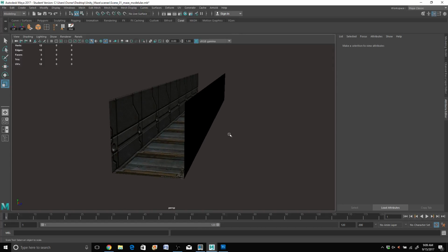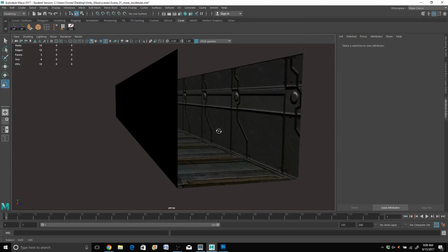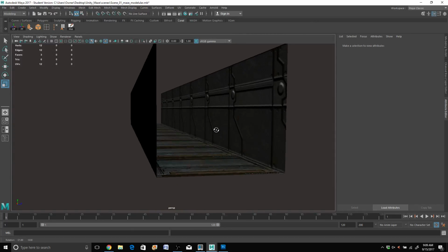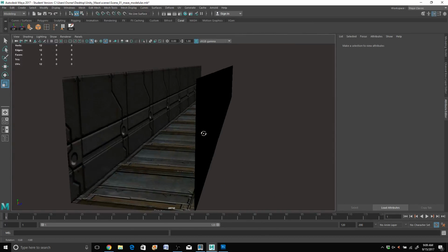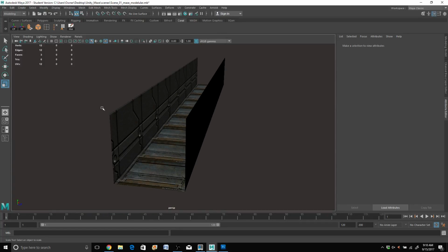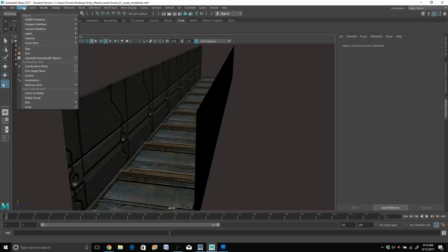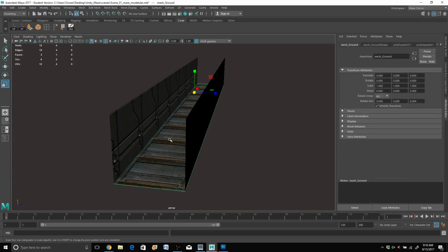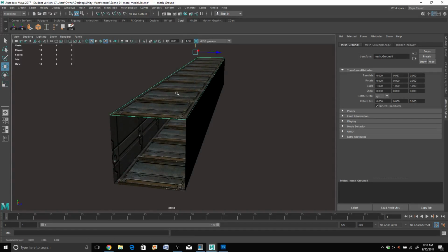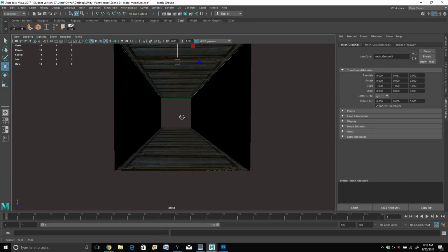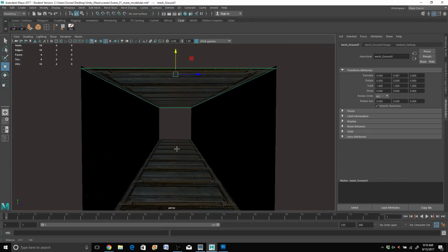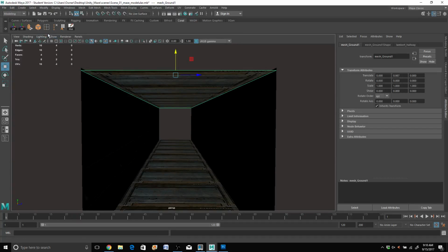If you want, we can go ahead and also add in a ceiling. Thing about ceilings though is that unless there is lighting in here, it's not easy to see. So let's create a mock ceiling to put in here, and it'll be its own piece. So you just push it off to the side and then put it back in there. But let's go ahead and create one anyway. We're basically going to make it based off of this one. We're just going to duplicate this one, bring it up, put it up over here. So this is created with the same texture. It'll do the same thing, top and bottom. But we can make it a little bit more interesting, right? What I'll do is add in some edge loops here.